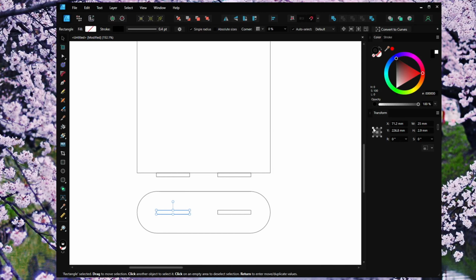And if I select this corner, for example, it will just extend from here to here. So if I do this again, you will see it extended just in one direction. However, we want it to extend from the center. So go over here again, select the center point, and enter 25.2 millimeter. Perfect. Same for the other one. Make sure center is selected. 25.2 millimeter.